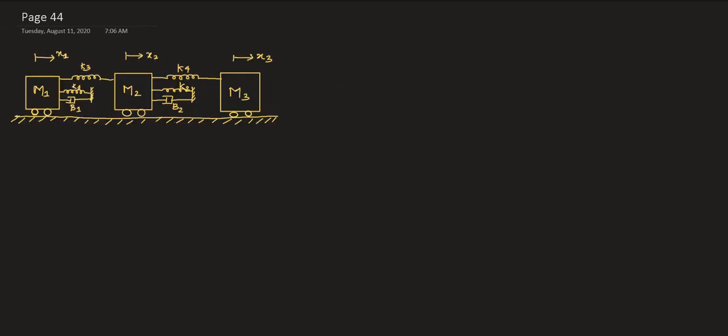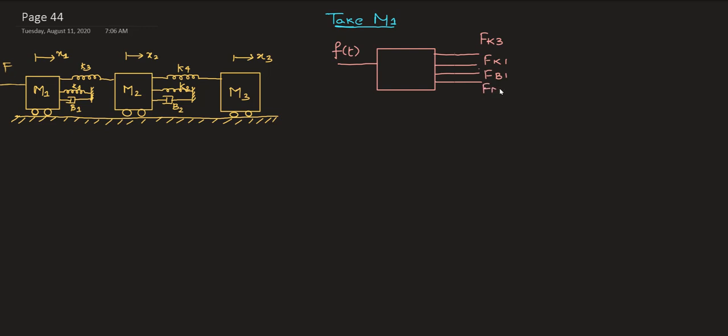The first thing we have here is the mechanical equivalent differential model, but what is the relative displacement? The relative displacement is for K3 and K4. If you take a closer look, K3 is between masses M1 and M2, and K4 is between M2 and M3. Keeping that in mind, I am going to write the differential representation for masses M1, M2 and M3, and then convert it into the electrical representation.